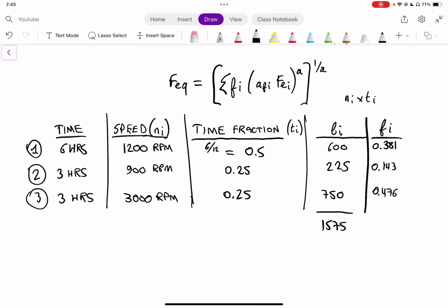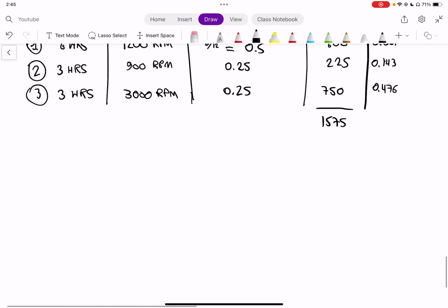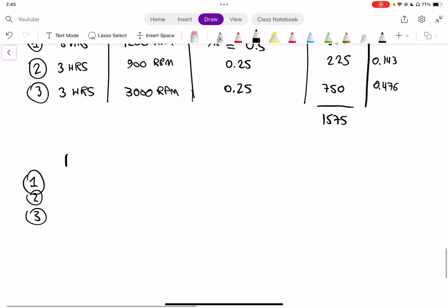So then we can keep going with our system, and I'm going to keep going with the table under here so that it doesn't go out of the page on the right side. We have our system 1, 2, 3, and the last thing I want to do is write our Fe value, which is going to be, in this case, equal to Fr. And then I want to write one last value, which is going to be Af times Fe, so that we calculate our Fe value multiplied by the application factor, because we see we have different application factors for different parts of the system.